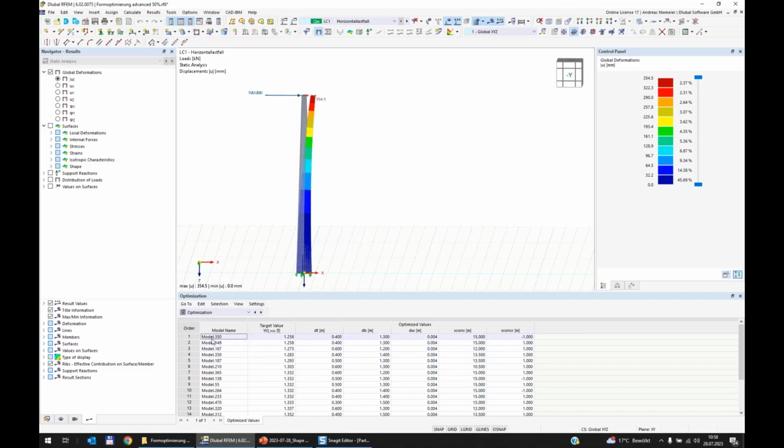the optimization that the program found within the 350th solution: a target value of 1.25 tons with a diameter of 40 on top, on bottom 1.3 meters, thickness 4 millimeters, no constriction, it's conical because it's 50 meters, and the direction is irrelevant because it's conical.